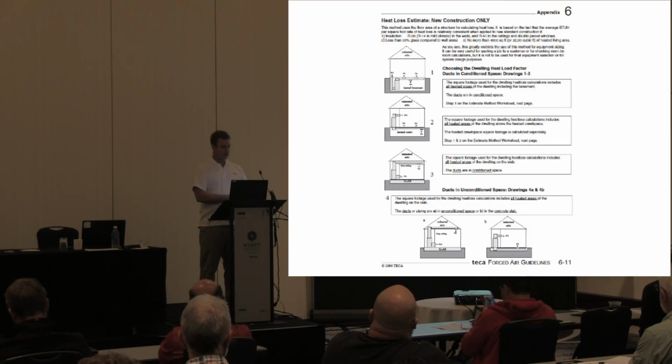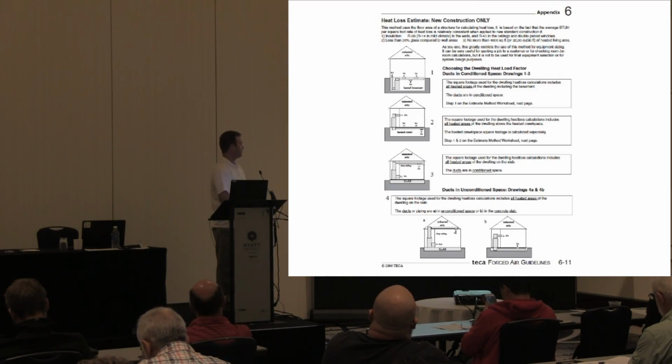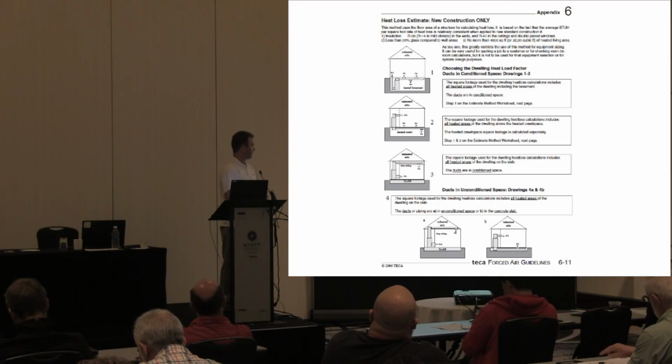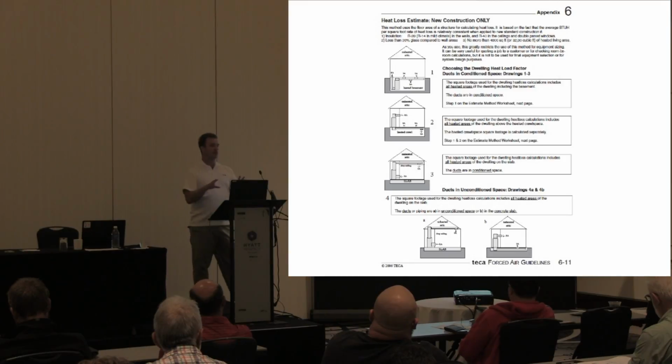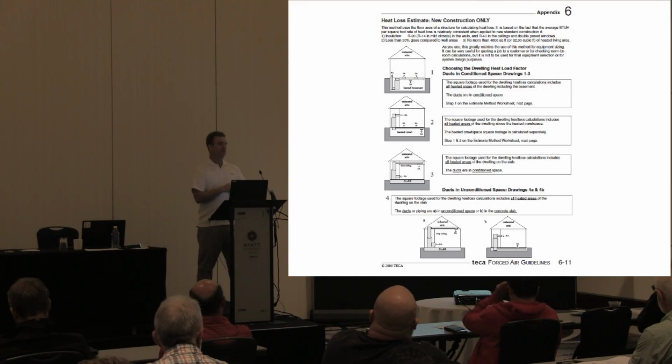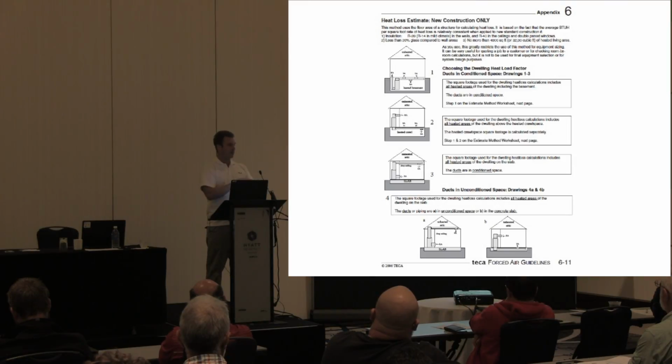So here's the quick heat loss calculation sheet that I'll explain to you, and it's on the next page. This is just the explanation. There are two ways to do the heat loss. One way is the way I just showed you: make your own form, use the factor, measure the outside walls, the windows, the ceiling and the floor, do that math, get an infiltration factor, and you're done. So you have about 6 lines on an Excel spreadsheet, and you're complete.